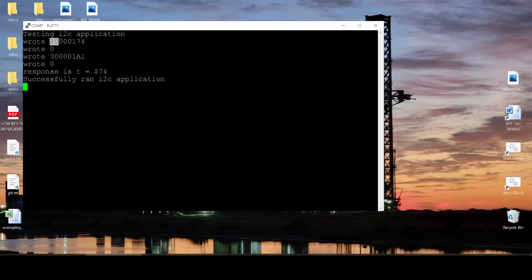In this case, of the 8 bits that are here, or even these 4 bits, bit 0 would be the write and read bit, where 0 is a write and 1 is a read. Bit 1, which is technically the second bit, being 1 would mean that it's valid. So in this case, 2 is a 1-0, so it's valid and a write.